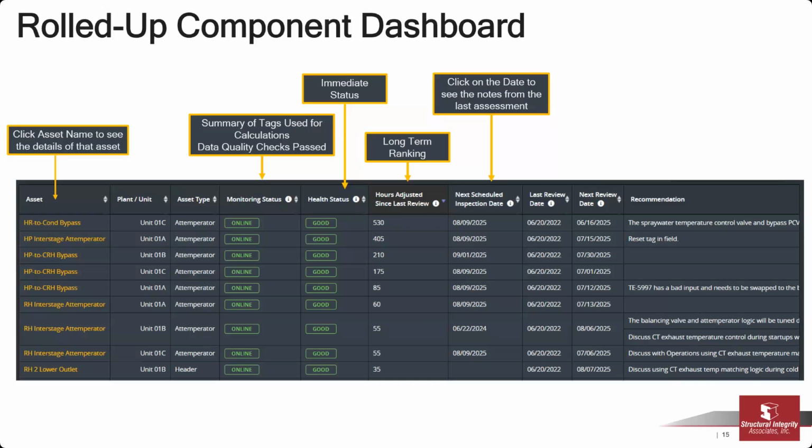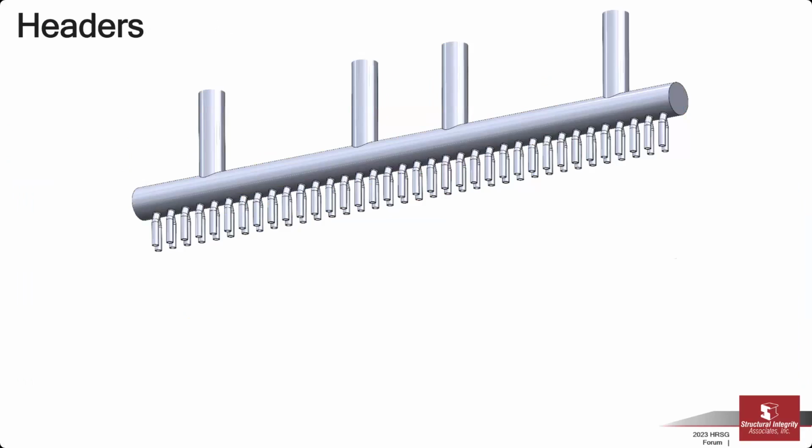So if they had done an inspection and we see that, hey, there's not accumulating much damage, then that gives us justification to push that next inspection interval out. Or if there's one that is having an attemperator problem or another fatigue problem, for example, we might accelerate and push it up and say, hey, it'd really be good if you get some more instrumentation even, or better dimensions, or get some material chemistry on the section. So it's all kind of linked together, but monitoring is kind of the overarching, I guess, driver to how we're tying it all together.